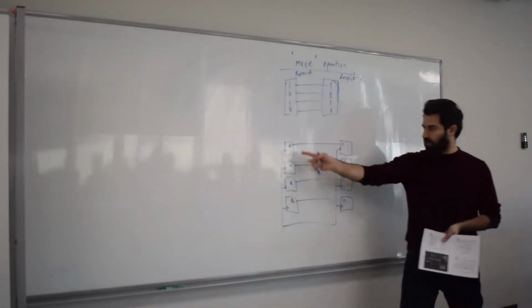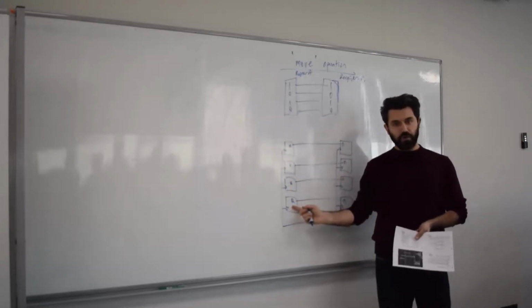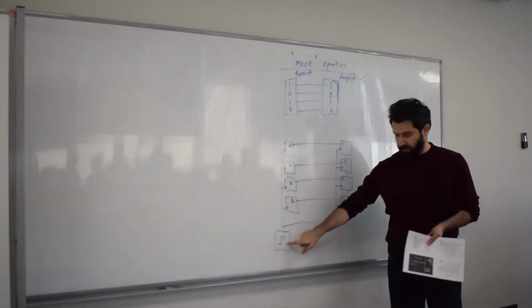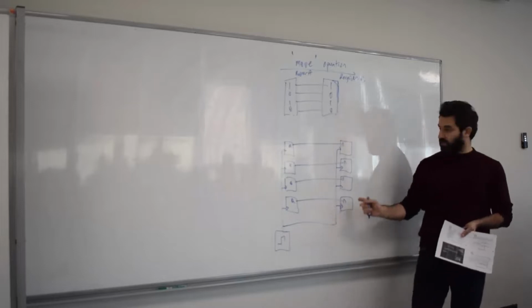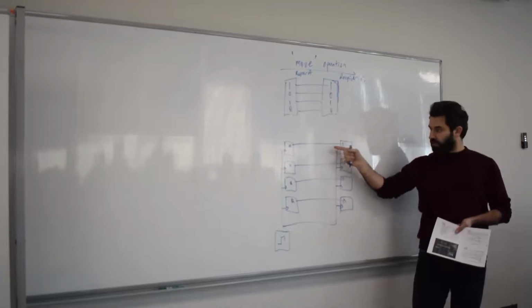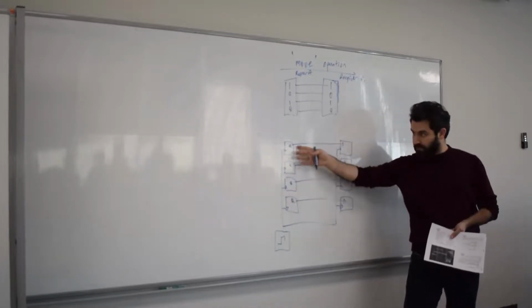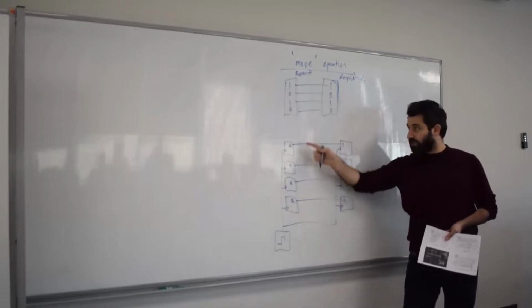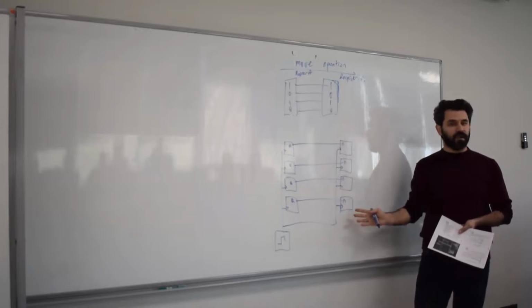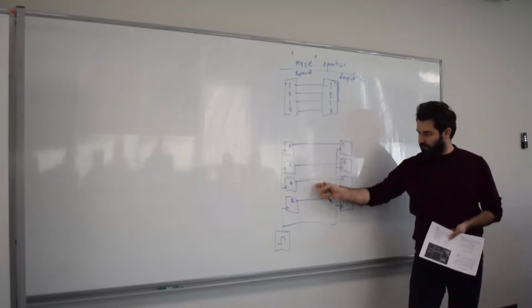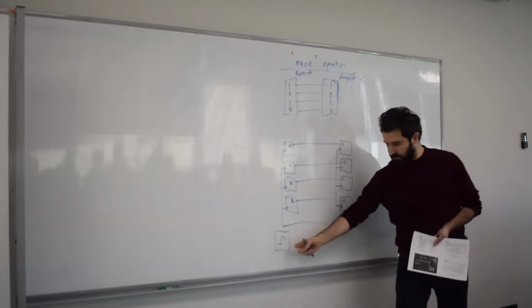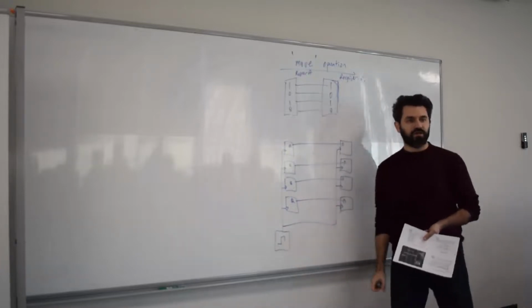It's pretty much it, because the 1010 stored in those flip-flops will be transferred in the next rising edge of the clock. What you do is basically enable these flip-flops to accept inputs, right? So you accept these inputs from these flip-flops, and these are the outputs, by the way. That means in the next clock cycle, these 1010 values will be transferred to these flip-flops directly. This is parallel because there are 4 different wires carrying independent information. The only dependence of these flip-flops is the clock. They are synchronized with the same clock.